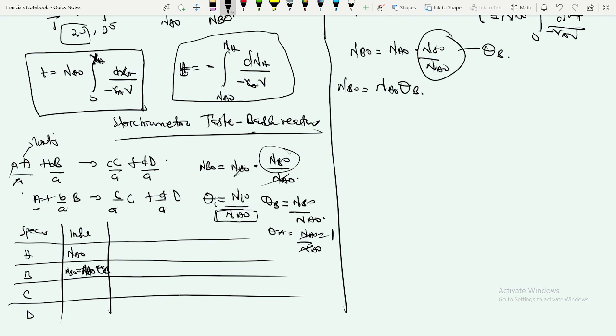So with C, if there are initial moles of C, sometimes you can have a reaction where we have a trace of the product already in the reactor, right? So our initial moles of C present, which is Nc naught, will just be Na naught phi C. Just like saying Na naught times Nc naught over Na naught, and this cancels this and I'm left with this.